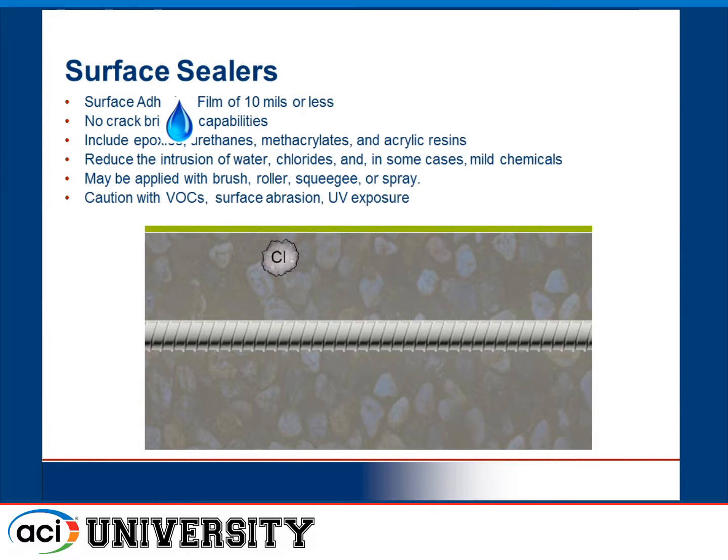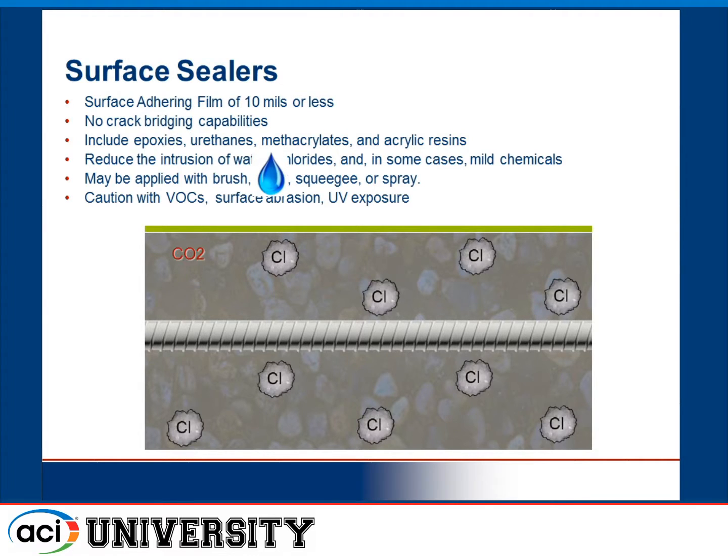What needs to be taken into consideration with any one of these surface treatments is that when we're dealing with structures that are already contaminated, there are species in the concrete already which could support corrosion. And although these surface treatments will mitigate the moisture ingress and might reduce the corrosion rates, they will not resolve the entire issue with contamination within the concrete.